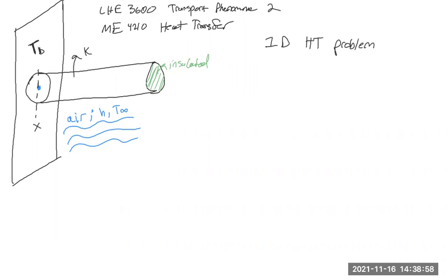So how do we find that governing equation that describes the temperature profile here? What you use is this technique of applying a differential control volume, and you perform an energy balance on this differential control volume. I'll pause here for 5 seconds, and I'll give you a chance to draw the differential control volume and set up the energy balance around that.